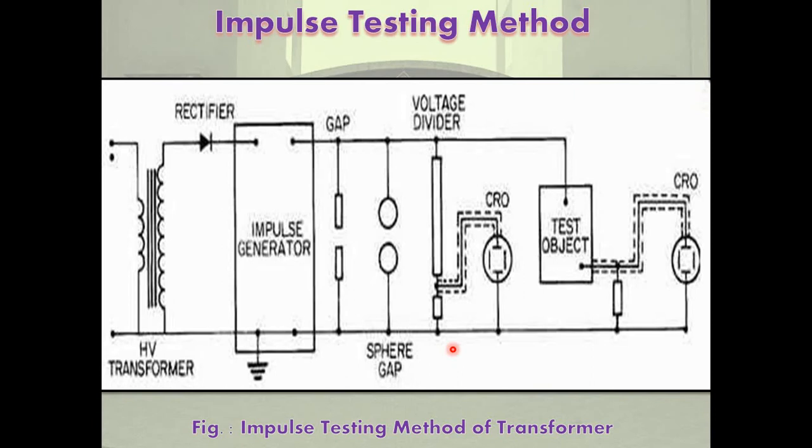The reading should be such that in one case, out of 6 applications of voltage, 2 or fewer discharges occur, and in the second case, out of 6 applied voltages, more discharges occur. An indicating voltmeter is connected on the LT side of the high voltage testing transformer. This voltmeter is calibrated by means of the sphere gap connected on the HT side.